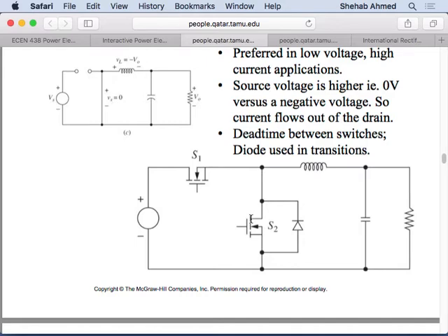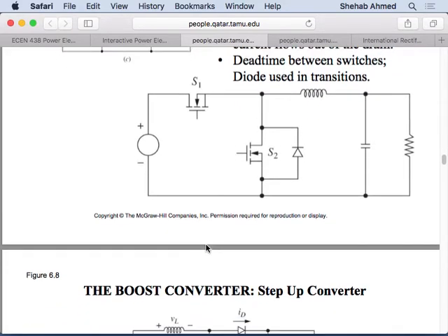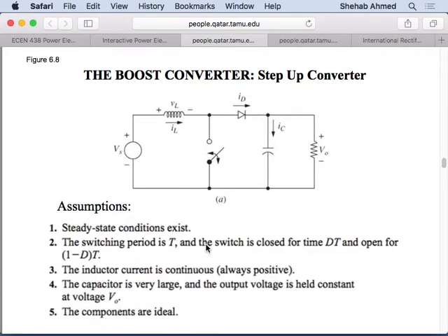So that's synchronous rectification, and this is something that's very common now in power supplies. Of course, the drawback is what? This MOSFET is an active device. You actually have to turn it on and turn it off, so you have to have a gate drive circuit along with that. So it's more complicated circuitry, so more expensive circuitry. But you're willing to put in more expensive circuitry at the expense of improving your efficiency. That's your call, depending on the load or a spec that you want to live with.